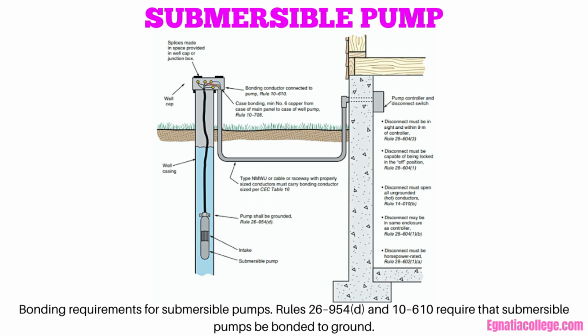The controller contains the motor starting relay, overload protection, starting and running capacitors, lightning arrestor, and terminals for making the necessary electrical connections. Thus, there are no moving electrical parts with the pump itself, such as would be found in a typical single-phase, split-phase induction motor that would require a centrifugal starting switch. The calculations for sizing the conductors, and the requirements for the disconnect switch, the motor's branch circuit fuses, and the grounding connections are the same as those for the jet pump motor. The nameplate data and instructions furnished with the pump must be followed.